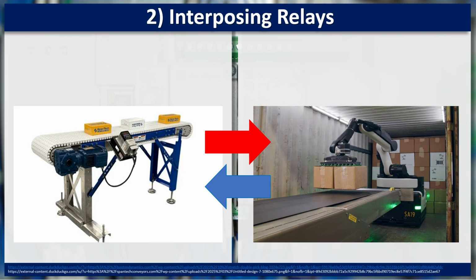Similar to the voltage control example, these machines are controlled from different electrical panels. We cannot simply connect a switch in one panel directly to the control circuit in the other. Instead, the two systems need a deliberate, compatible interface to exchange their ready and clear signals. An interposing relay can provide that interface while keeping the two control systems electrically isolated.